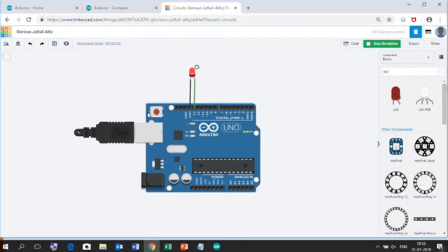Did you see that? With the start simulation, the USB cable got connected here and this LED is blinking. Why? By default it's blinking since it's connected to the pin number 13 and it's an inbuilt LED. So you can see that the inbuilt LED is also on here.